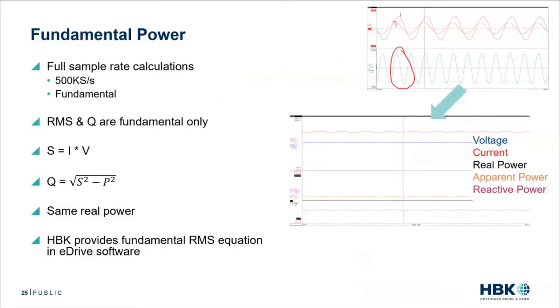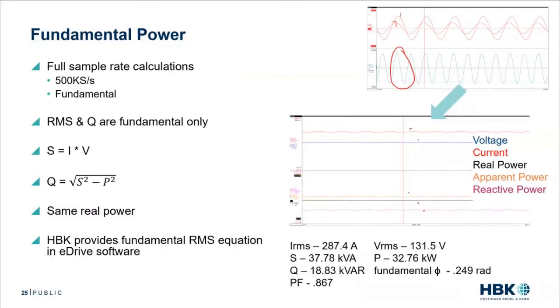And if we do our equations, again, RMS voltage, current, apparent power, real power, reactive power, we measure our values, and we get even a little bit more decrease. So 2 kilohertz got us most of the way there, but not all the way to the fundamental. And what we'll find is the exact same equations. We've run this fundamental calculation to really isolate the fundamental RMS voltage and current. That fundamental is if everything was a pure sine wave, that would be our value.